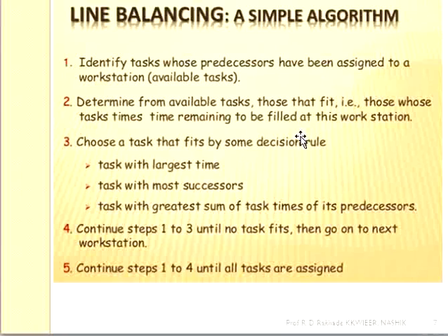And next step, determine the available tasks, those that fit and those that take time remaining to fit at this workstation. It means after calculating the time required for any workstation, we club the respective tasks to fulfill that workstation time.